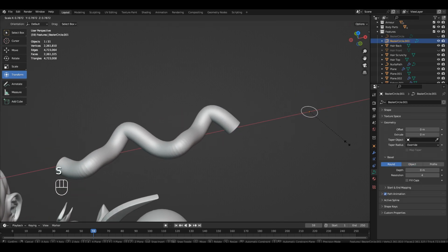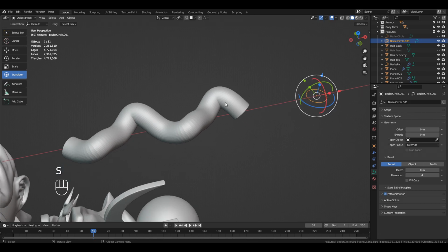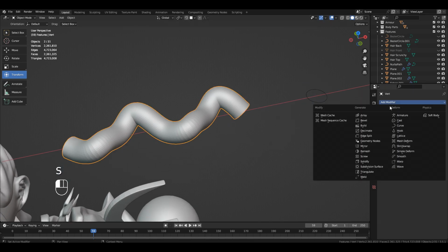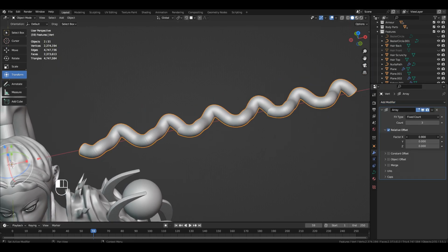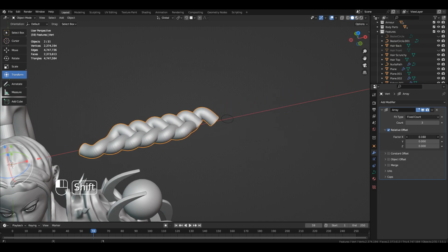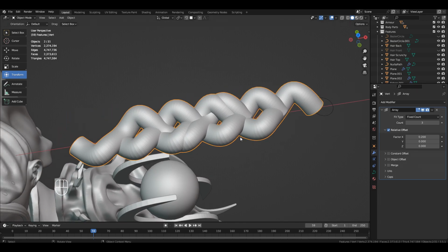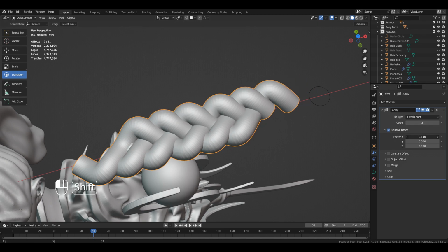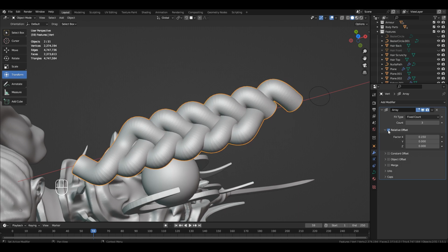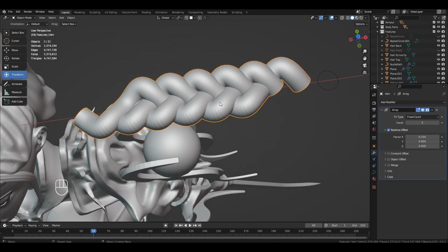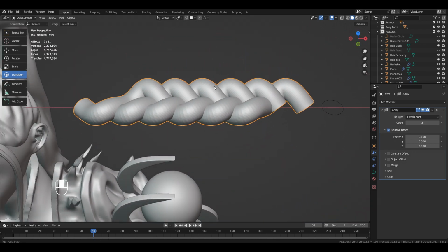This will then form the depth and the length of your chosen hairpiece. Then we'll select back onto the Bezier, apply the array modifier, set the count to 3, and push it in together using the X modifier on the array modifier tool. And voila, we have our braided curve with the 3 modifiers, and we just need to put them into place. Sometimes you might need to use the Y or Z axes to fine tune it, but if you've done the measurements correctly at 0.2 and followed along, it should look similar to this.